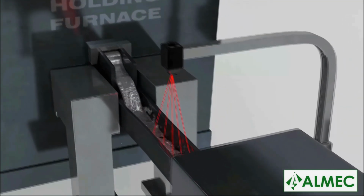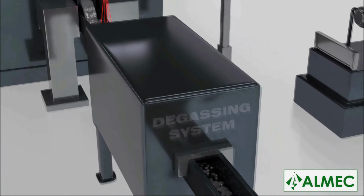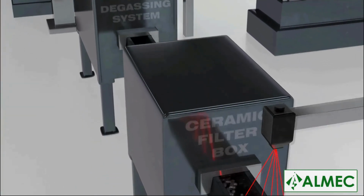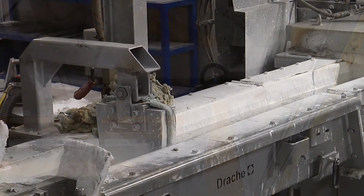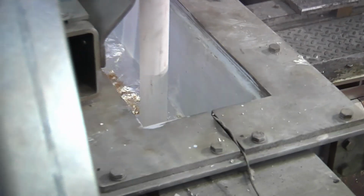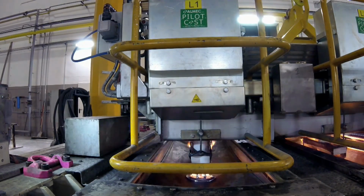The metal passes through the degasser and the filter and arrives at the dam positioned before the launder. The level of metal is detected by the launder laser. The metal fills the launder and dam opening is requested when the level exceeds the opening position. During the first moments of the cast, the system performs various safety checks.